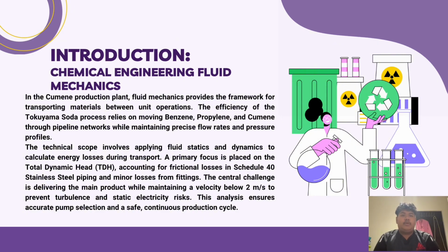A primary technical focus is managing the pressure drop across our system by calculating the friction factors and Reynolds numbers. We ensure that our pumps are sized correctly to overcome the energy losses, maintaining steady, efficient flow through the reactors and distillation columns without compromising safety.